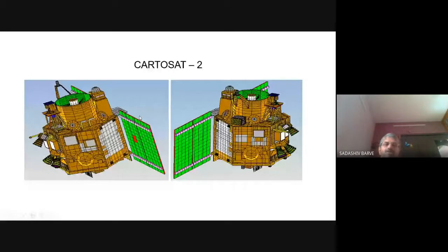So this is the typical picture I just showed of how the elemental calculation is done. For example, this is a solar panel, and we can estimate how the temperature distribution takes place from one end to the other corner. This is applicable for a satellite also. This area is called the radiating area, what we call the OSR area, which I will explain in the next lecture. That is the radiating area for the given panel. So this is how the modeling is carried out.